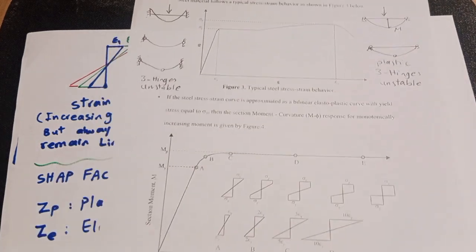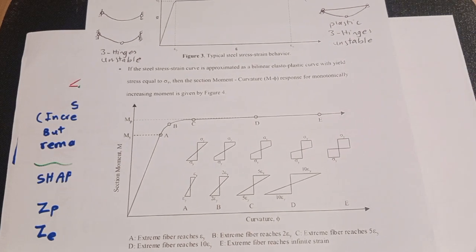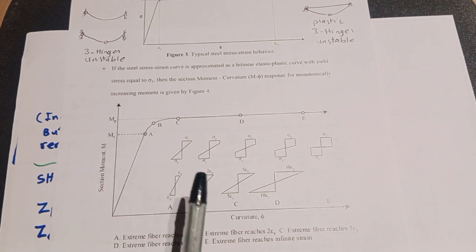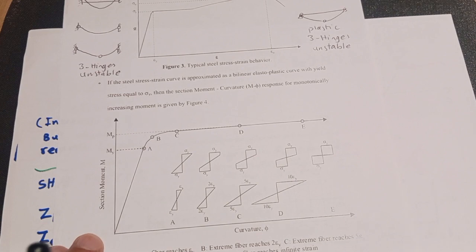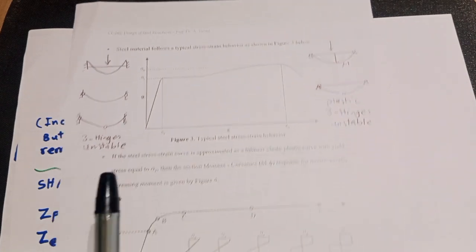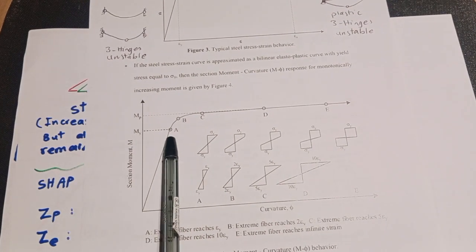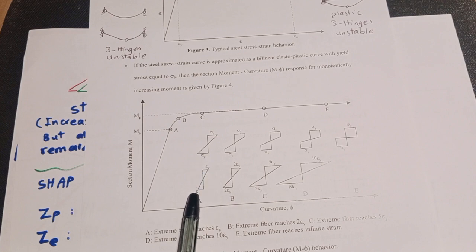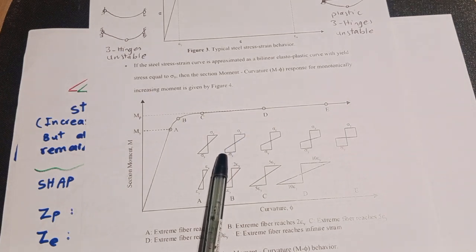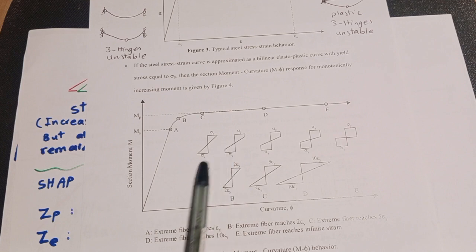Here I have this explanation in the range of a moment curvature curve, or the same for the sigma epsilon, stress strain curve. Up to point A here we have the elastic range for stress and strain, both linear. When we reach point B, strain is still linear but increasing, but stress reaches the final Fy point and transfers to the next level, and Fy is the extreme point for stress.